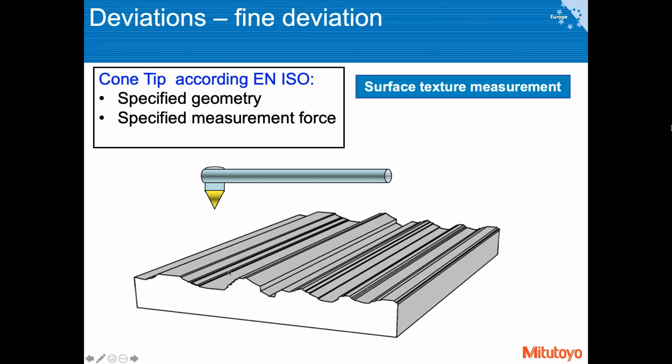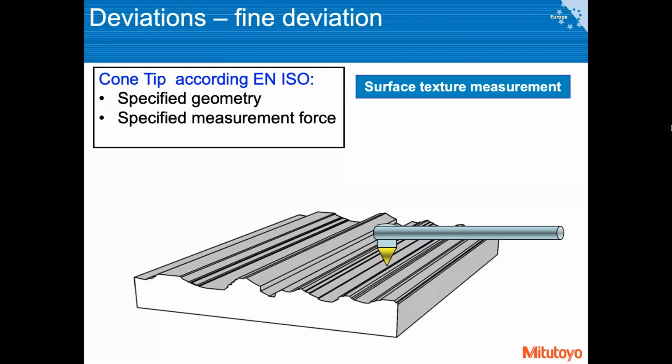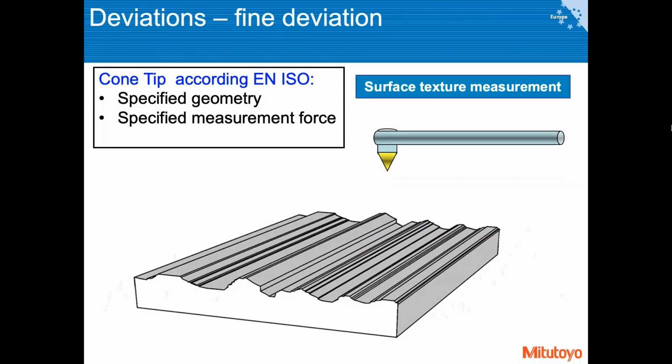So if this is a kind of sketch of our surface which we want to measure, the most typical and least expensive method is using these profilometers. And the profilometer works basically as it has this stylus. At the end of the stylus you have this needle over here, and this needle simply slides across your surface like this.